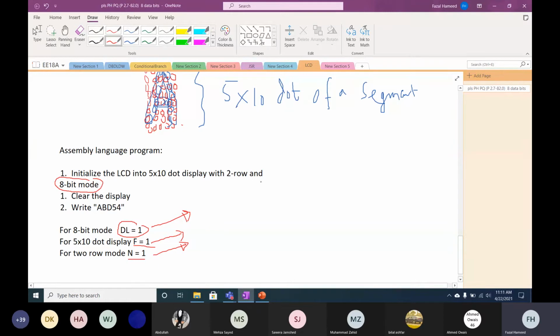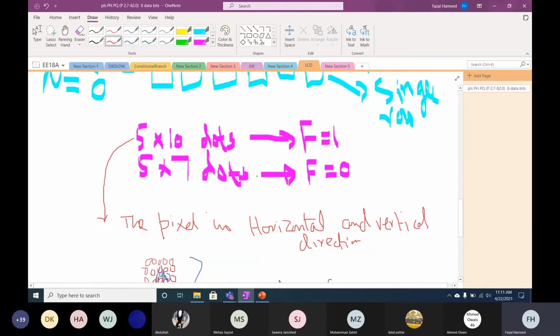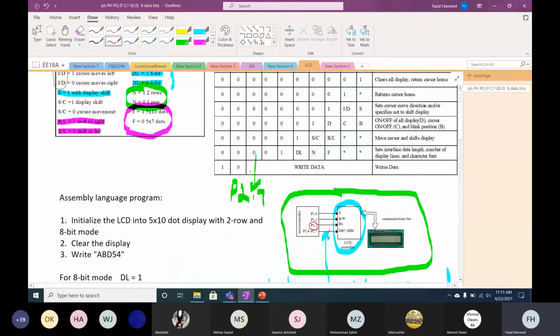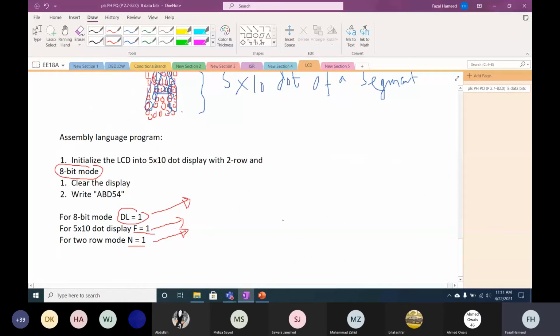Okay. So if we want to initialize the display and send some command to the LCD controller, first we have to send some data to the LCD controller and then we have to send a pulse on E. What should this pulse look like? It should look like this. E is initially 0 and then we write a pulse.